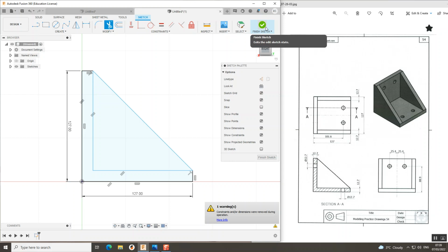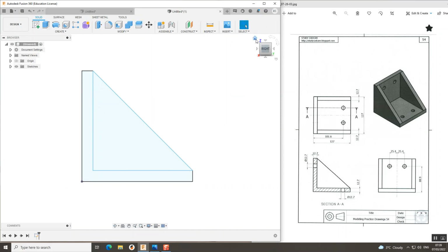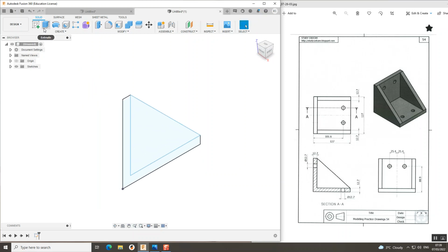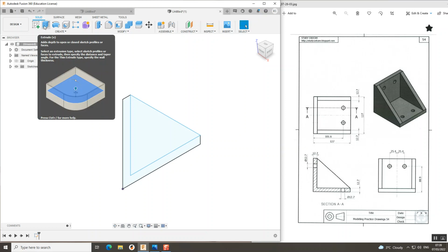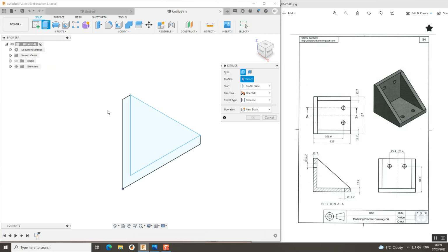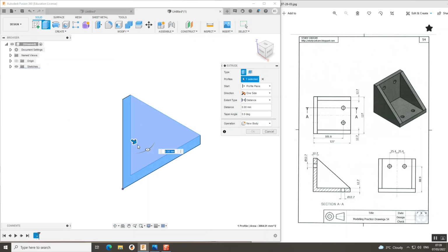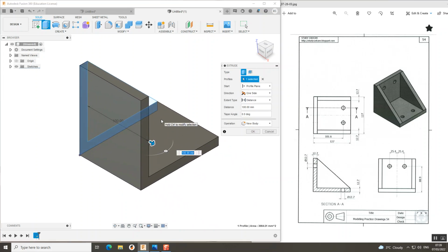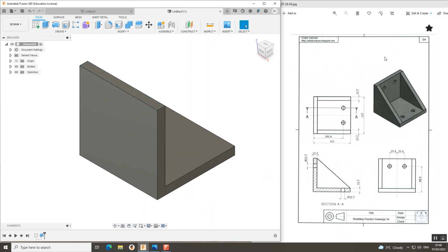Now at this point we've actually finished the sketch and now we want to move on to the actual 3D modelling. So I'm going to click Finish Sketch. I'm going to click that Home button in the top right to change my viewpoint, like so. And I'm going to extrude it, using the Extrude tool, which will basically make it 3D. That line there, and I want to bring it across 127 based off the measurement you see over there. So 127 and then click enter.